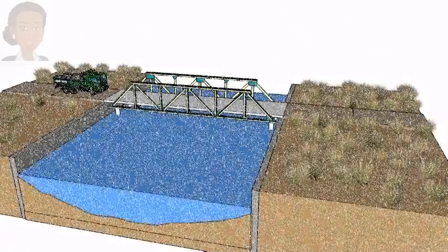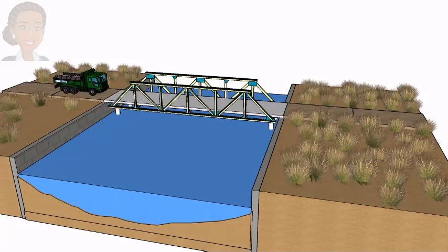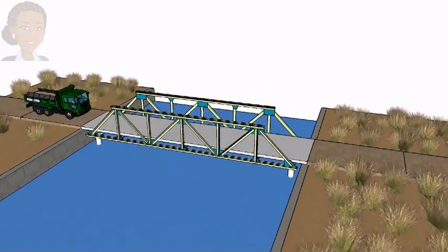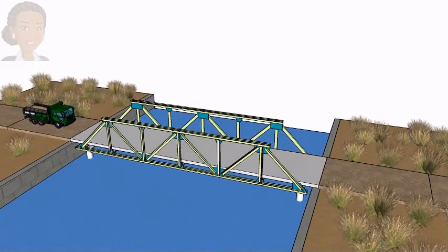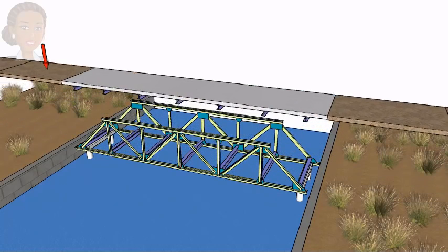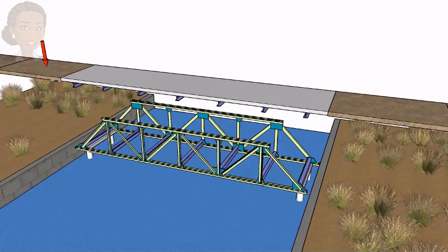We can solve this problem using influence lines. But before we get into the analysis details, let's visualize how the load transfers from the truck to the truss joints. In this visualization, I am going to assume that the entire load of the truck is concentrated at its center of gravity. As shown here, the bridge deck rests on 7 beams, each attached to 2 truss joints, one on either side of the bridge.